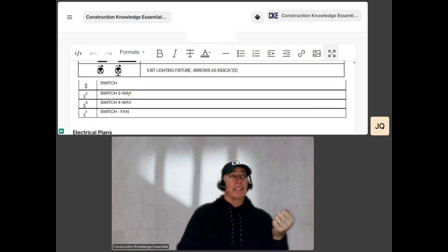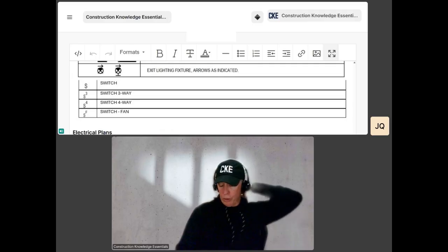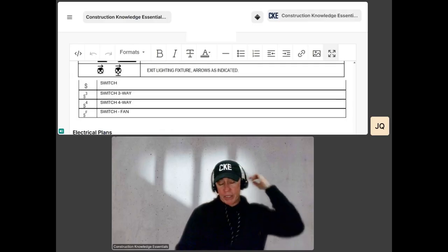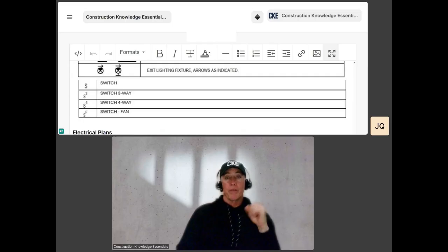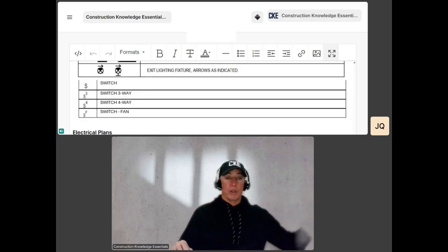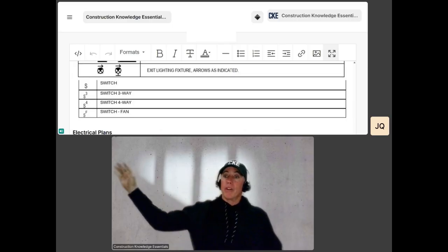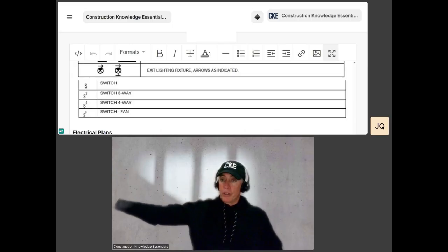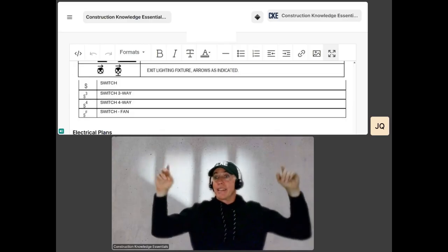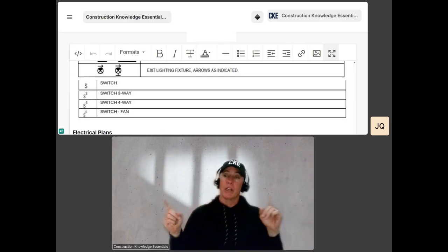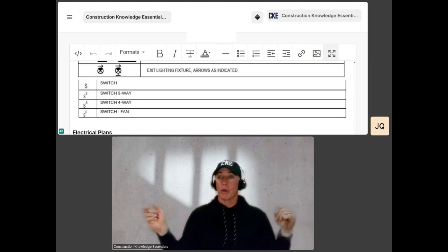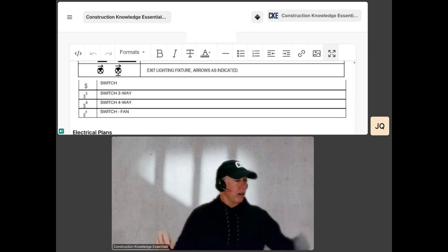Developments have that. That's just the sort of thing. Switches. You ever in your apartment or your house have a three-way switch? Now, a three-way switch does not mean it switches at 3 locations. It means it switches at 2 locations. So a three-way switch means if you're at one end of the hallway and you have a switch and it controls the lights above you, and then there's another end of the hallway where there's a switch, and it also connects that same light. That's a three-way switch. And that switch turns it on and off depending on where you're standing. You can flick it on there, flick it on there. It'll do the same thing.